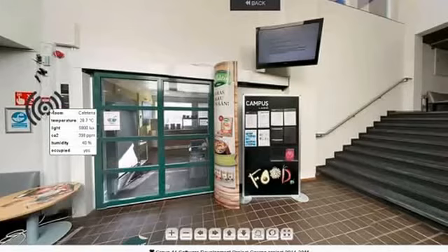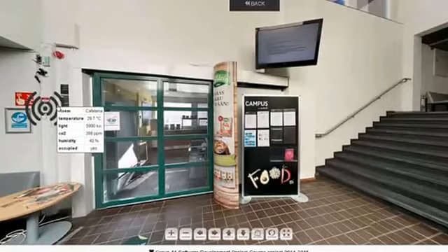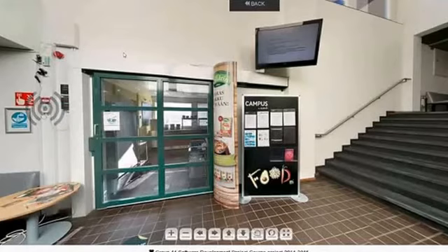Now the purpose here is not just to install sensors and get values from them. It's really about that when we install these sensors, they publish immediately that now I am here in this place and I can provide you with this information: temperature, light, CO2, humidity, and occupancy information. Then the building, as well as this whole visualization tool, can know that now I have a new information system, a sensor that provides me with this different information.